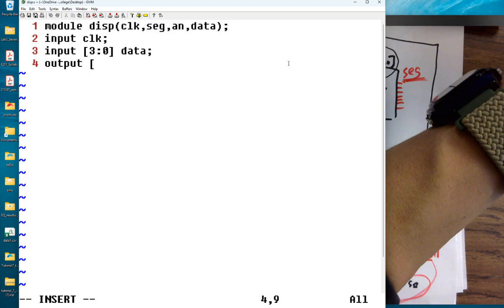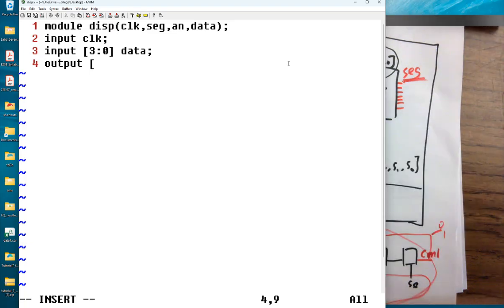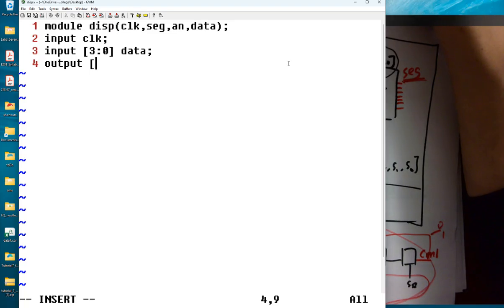Did I do that? Oh, because these are not FPGA modules, right? These are not FPGA modules, and you may need to change some of them into register type. But for now, usually, output should be registers if they are being included on the left-hand side of the procedural assignment in the always block. But for inputs, we usually don't do that. It's gonna report syntax errors. No reasons, Verilog just doesn't like it. It's basic rules.